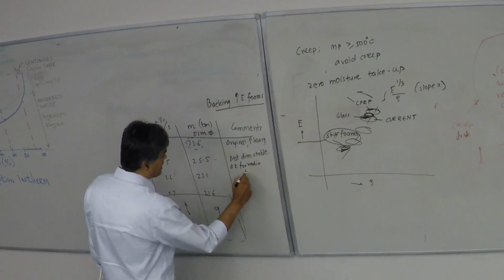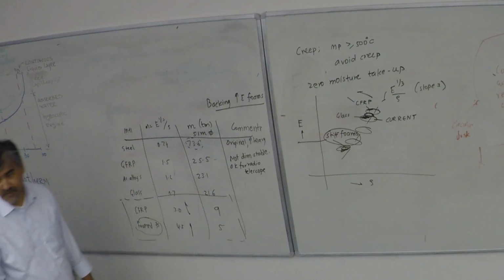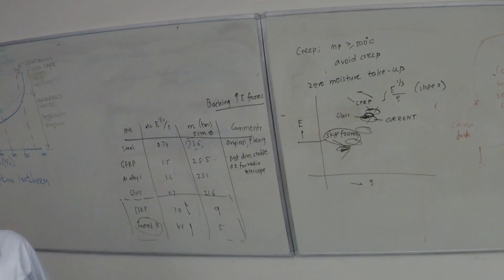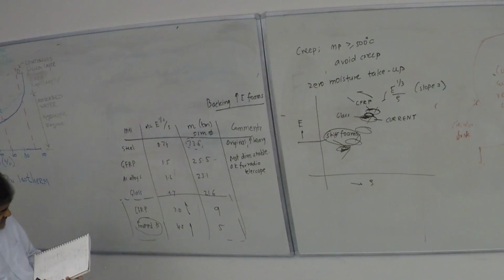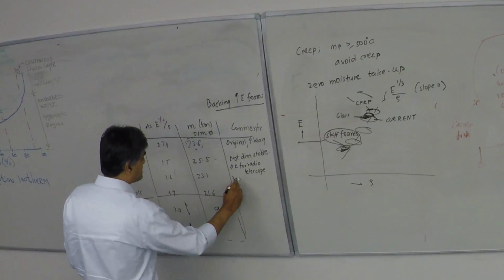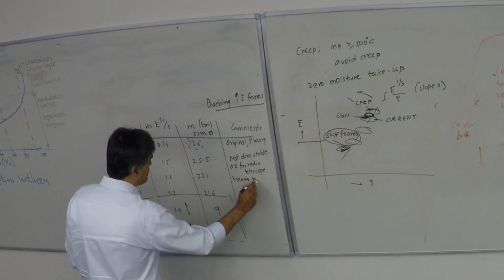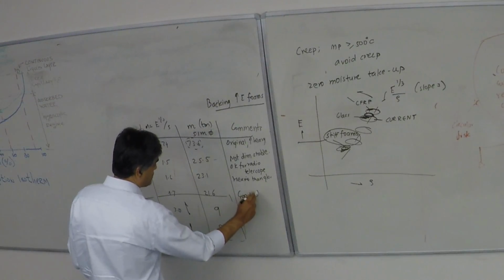And they say that this is okay for radio telescopes. I'm no expert at telescopes, but I believe radio telescopes have longer wavelengths, typically, and when the wavelengths are longer, they are more forgiving. In optical mirror telescopes, you've got to have extremely short wavelengths, so the precision becomes even more critical. But GFRP could well be used if the application is slightly different. Aluminum alloys is an option, but it's heavier than glass. Glass is a good choice here. For example, that is what is used.